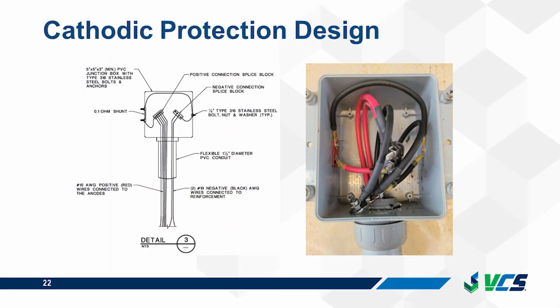But also, does the anode have to be physically connected to the rebar, or does it work just attached to the outside? Because these are monitored jackets, the anodes are not directly attached to the rebar. So the anodes are attached to each other, and then there are 2 anode wires. So right there you have the 2 red wires. The 2 anode wires go into the junction box, and then the black wires are the structure wires.